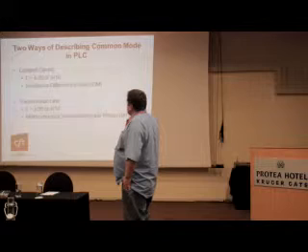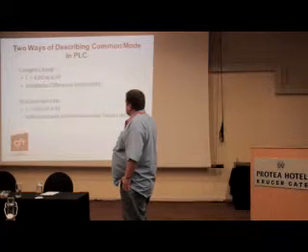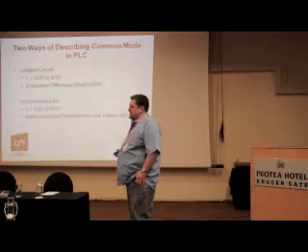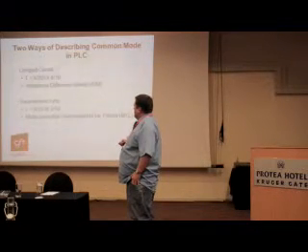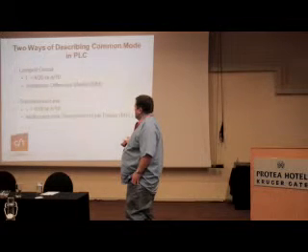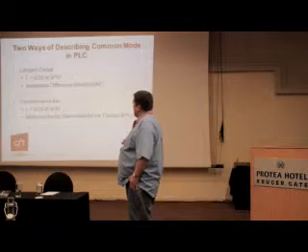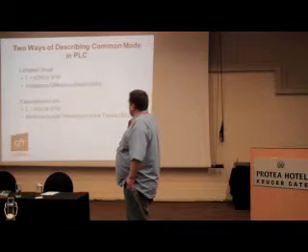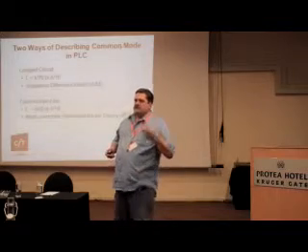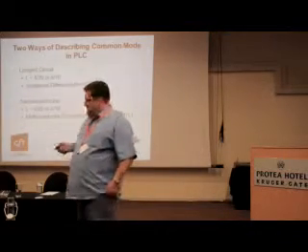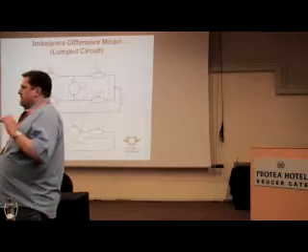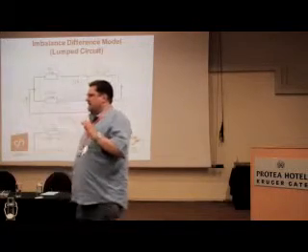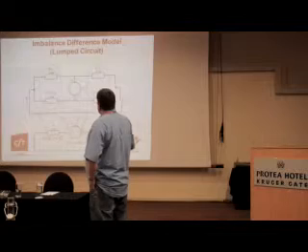Now, this is a so-called electrically short system, where lumped circuit theory dominates what happens. If you're looking at systems where the length of the PLC line is larger than lambda over 20, we start using multi-conductor transmission line theory to explain how common mode actually works. I'm not going to bore you today with this, but this is one of the things that we are looking into and trying to understand, and it's called the imbalance difference model.